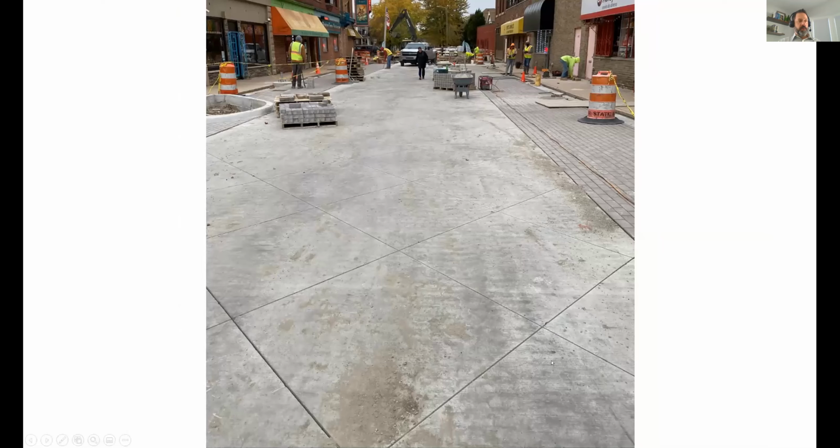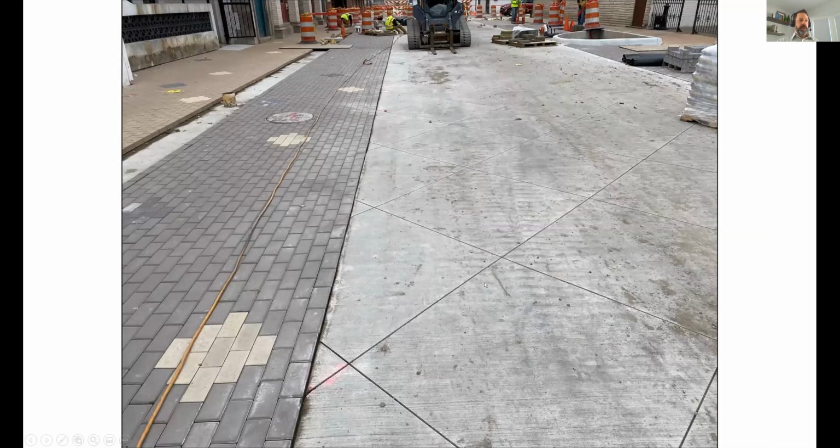Here's another one we've looked at with a 45-degree joint pattern. The issue with these is that we worry about these little chunks breaking out over time, as well as them not actually cracking the entire way. I would have rather liked to see this type of detail where the two combine and go perpendicular to the edge where they meet the edge of slab there.